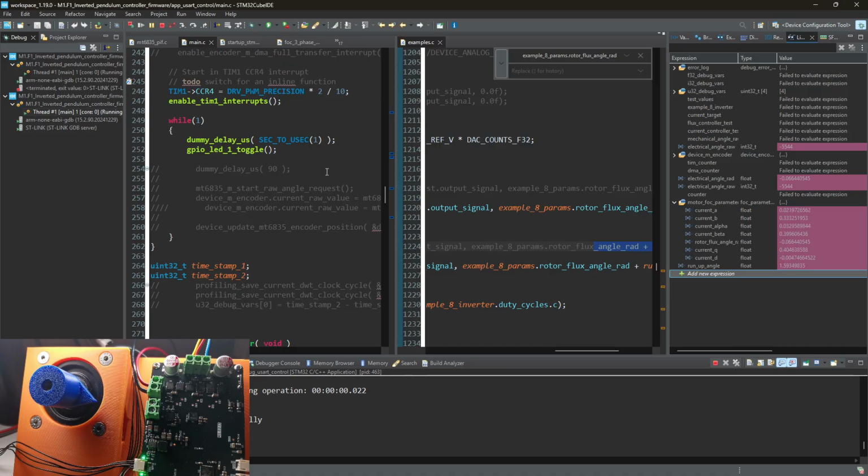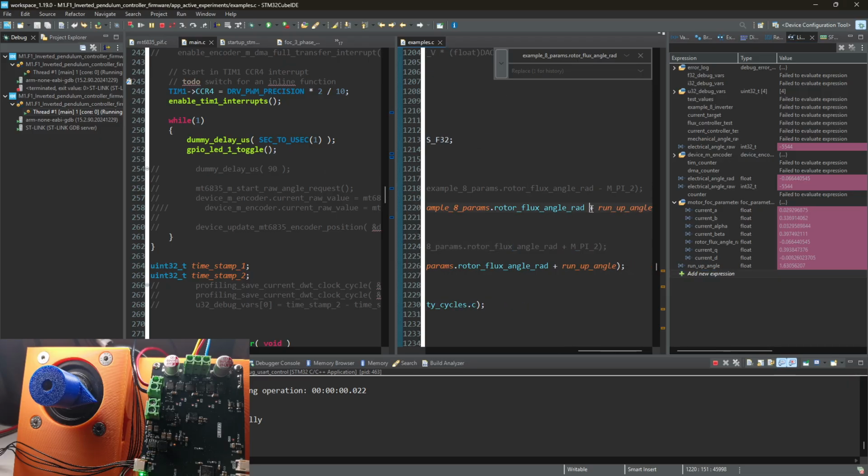So our current implementation tries to force our rotor to a pole, to each pole. But it's supposed to do the opposite. It's supposed to move our rotor from the pole. And if this is the case, let's try to change the sign here. Yes, exactly. I have 8 steps exactly because of this reason.